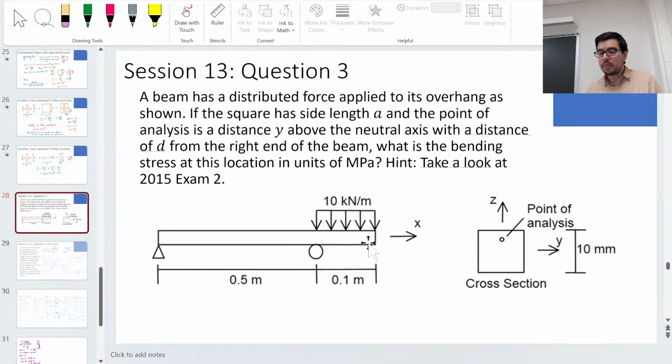Another approach, okay, is to take a slice and cover up the left, okay? So if we take a slice and we cover up the left here, right, and then we're looking at that, then we only have to account for what's happening to the right. And you need to do careful equilibrium there, okay, but that's potentially an easier way to attack the problem, okay?